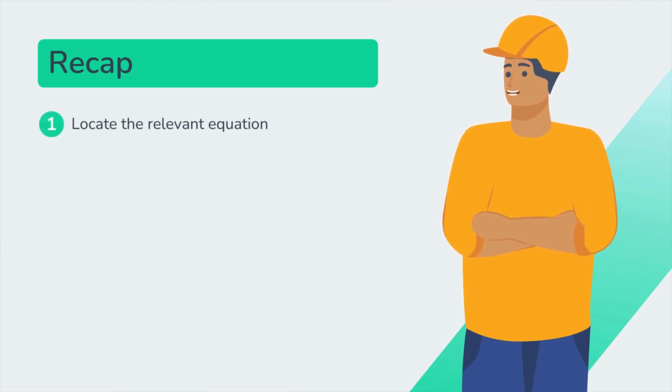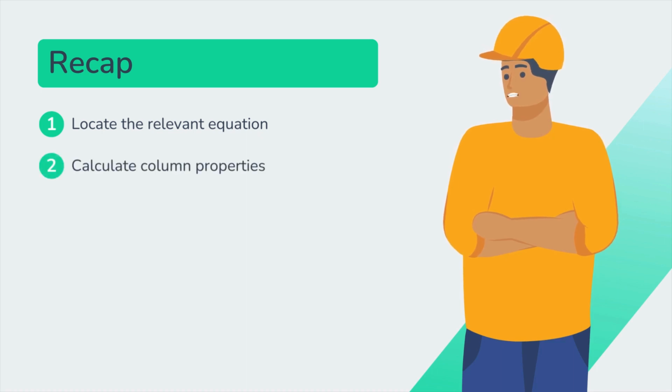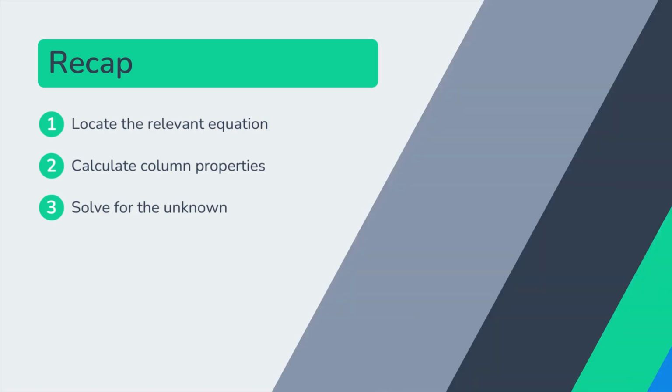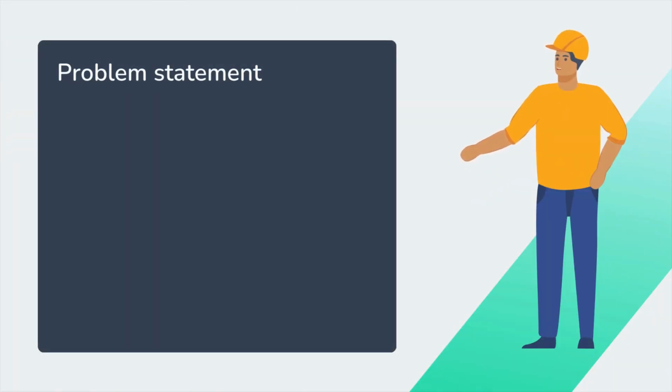1. Locate the relevant equation. 2. Calculate column properties. 3. Solve for the unknown. Imagine we have a steel column.